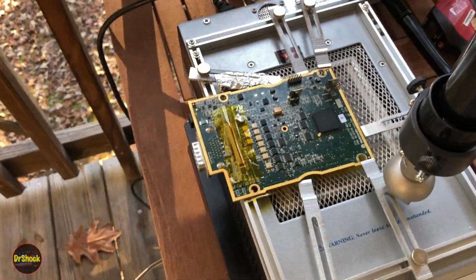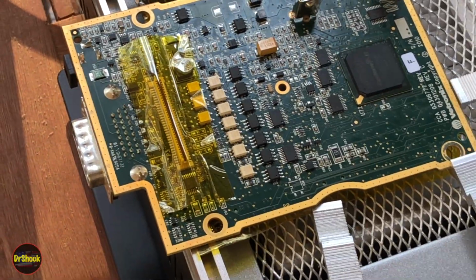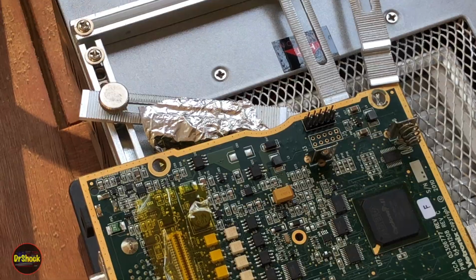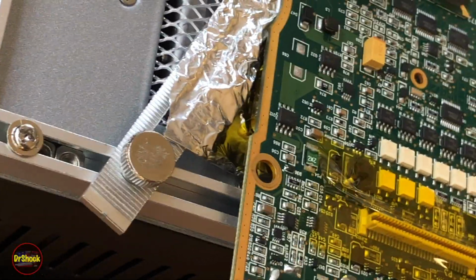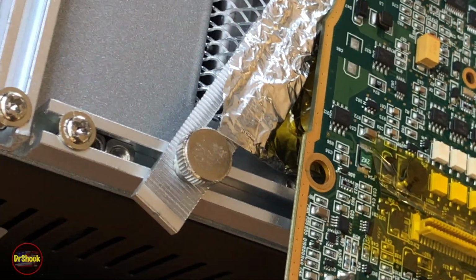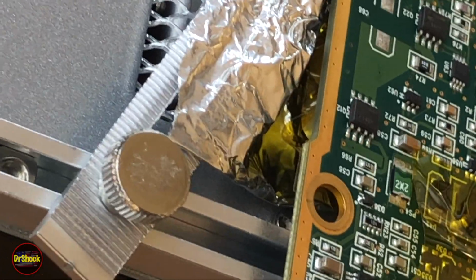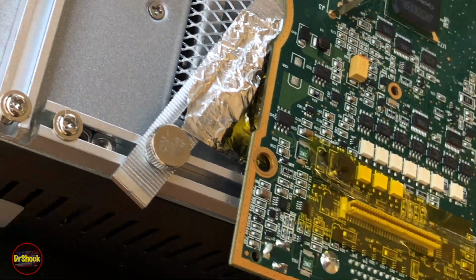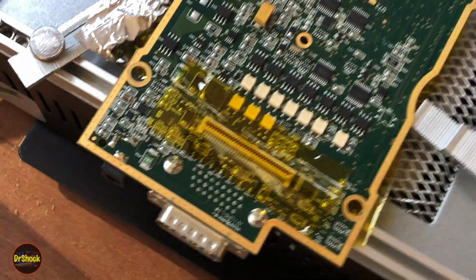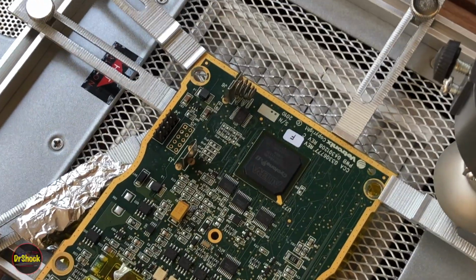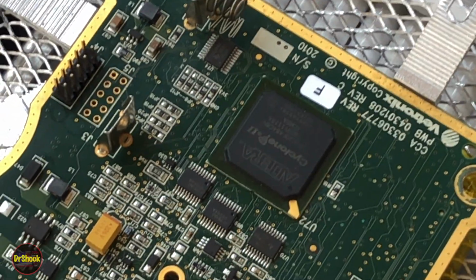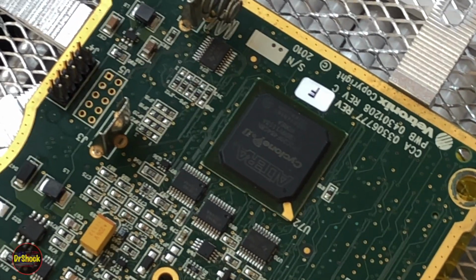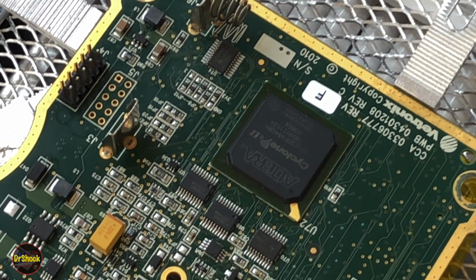All right, guys, here's the setup we've got for this board. We've also added a little piece of aluminum foil over those two electrolytic capacitors just to give them a little bit more insulation and insurance so they don't pop on us. They also have Kapton tape on them, as well as all three of the plastic connectors. So we've got the cyclone centrally located so they can get the most of the heat. We'll try to get this over with nice and quick before we damage any of these other components.